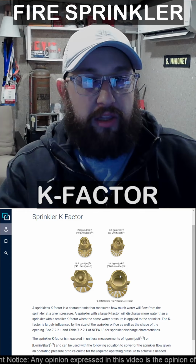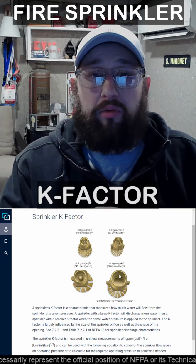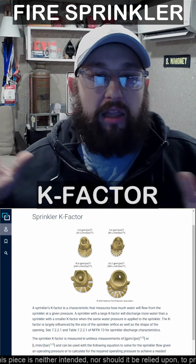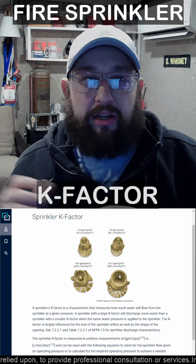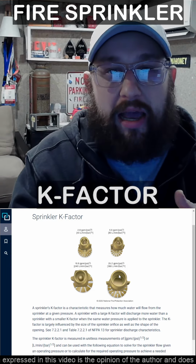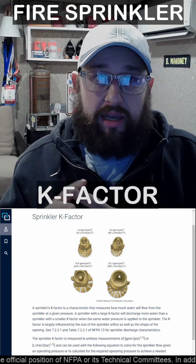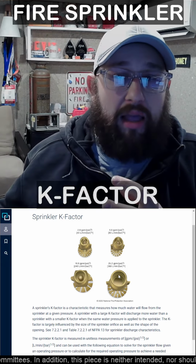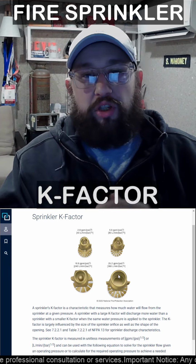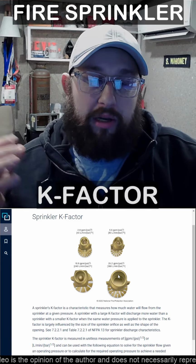And you play with the K factors a little bit in order to help with the design of a sprinkler system. Typically, the lower K factors are going to be used in lower hazard areas where we don't necessarily need as much water. 5.6 is going to be kind of like your most common K factor. 2.8 is kind of small. That's more on like the residential side. And then as we get up to bigger K factors, we're going into like storage type areas or higher hazard occupancies where we need a lot more water. Now, just remember, the higher the K factor, the bigger the hole, the more water that we're going to get.